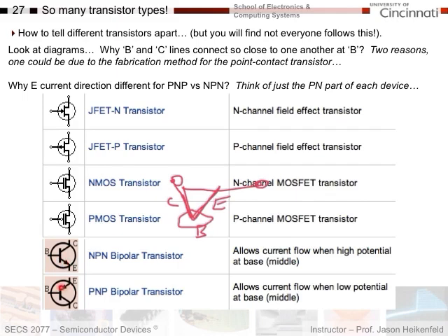Well, this arrow here is called a PNP bipolar transistor, and that's the one we've been talking about. The reason why the arrow points into the device is because for a PNP bipolar transistor, we emit holes into the base, right? They go from p-type material into the n-type base. Well, holes are a positive carrier, right? And so that is current flow from the emitter into the base.